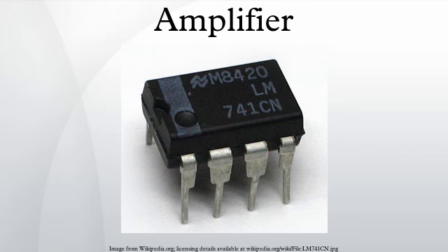Single-ended and triode Class A amplifiers. Some hobbyists who prefer Class A amplifiers also prefer the use of thermionic valve designs instead of transistors, for several reasons. Single-ended output stages have an asymmetrical transfer function, meaning that even-order harmonics in the created distortion tend not to be cancelled. For tubes, or FETs, most of the distortion is second-order harmonics, from the square law transfer characteristic, which to some produces a warmer and more pleasant sound.